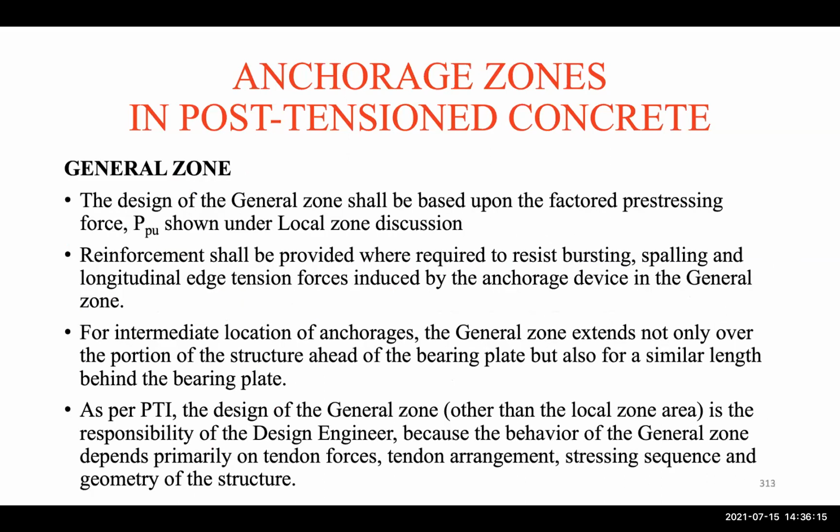And then we have the general zone that has to be designed. For that we have to consider P sub U under the local zone, and then reinforcement shall be provided where required to resist the bursting, the spalling, and the longitudinal edge tension forces induced by the anchorage device.